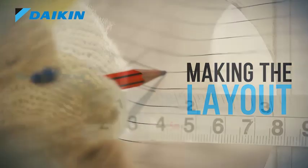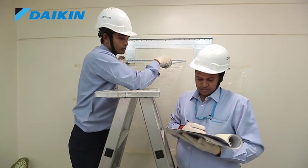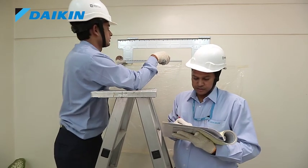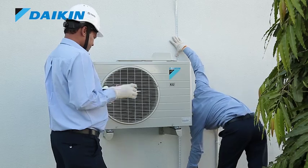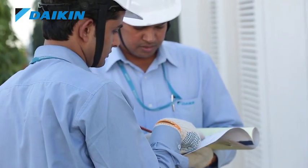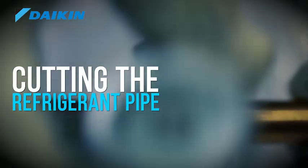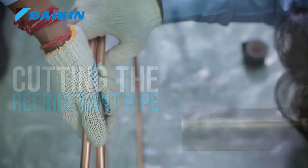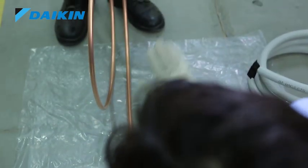Making the layout. As per the location of the indoor and outdoor unit, take the measurement and make a layout for the piping with dimensions. Cutting the refrigerant pipe. As per the layout, the required length of copper pipe is to be cut from the pipe roll.